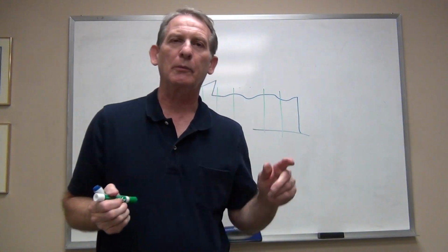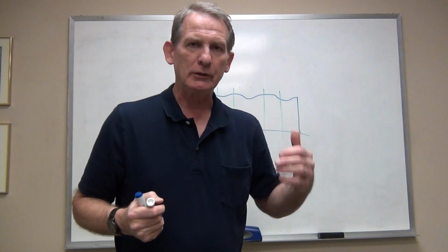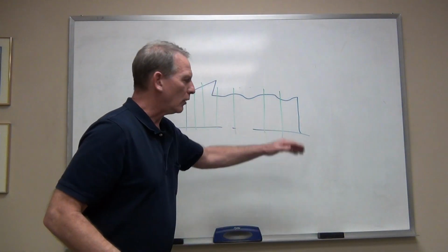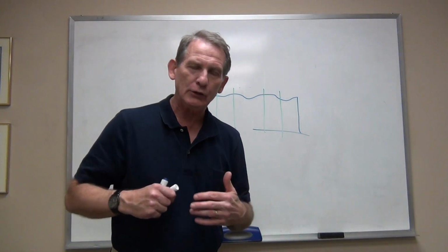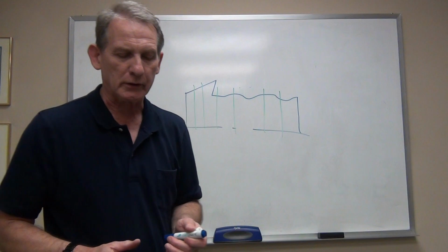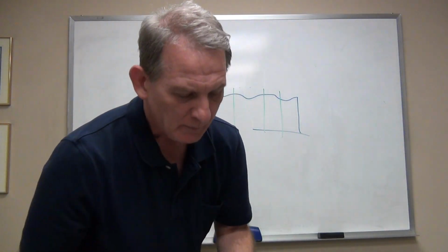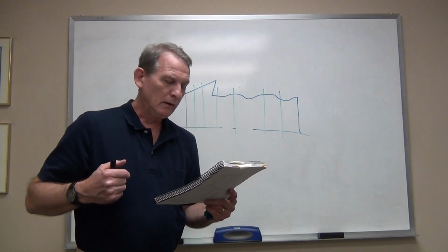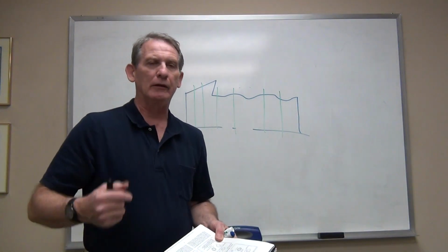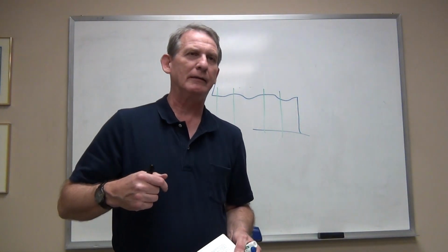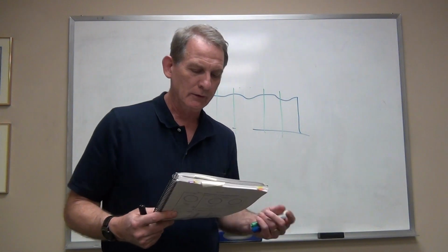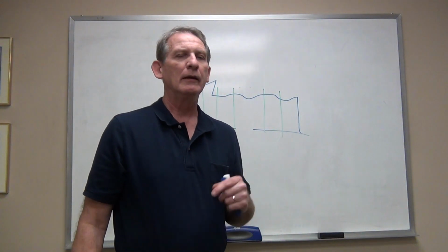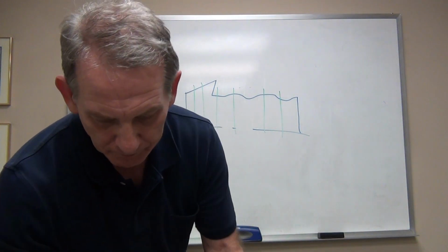That is all we are concerned about, a circle, which is a two-dimensional geometric feature. So we look at all of these circles down the length of it and evaluate each one of them independently for circularity within a certain tolerance. And we can go on and on with this. You can actually have circularity of a sphere. So if you wanted to check the integrity of a ball bearing, say, you could use a circularity call out, because no matter where you slice that sphere, it is always going to be a circle.